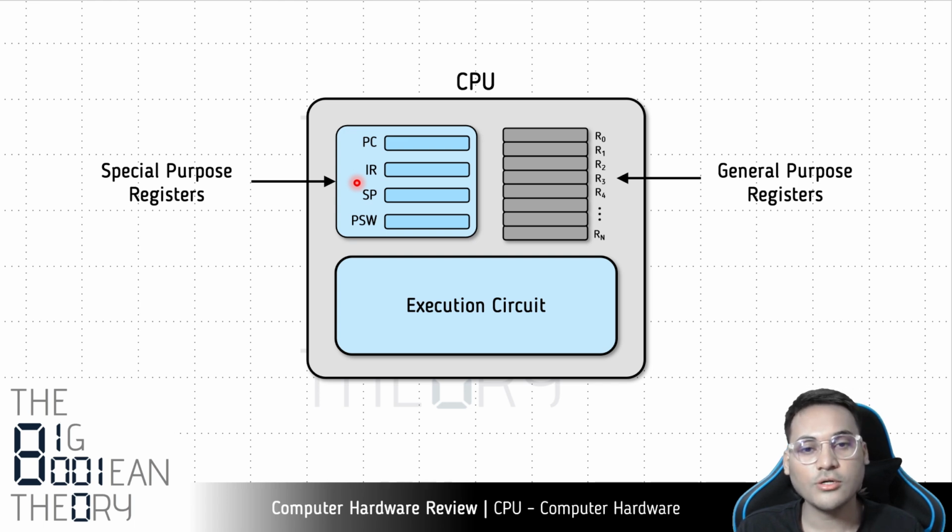And then let's talk about the program status word. Program status word is basically a collection of different flags, right? A register has many bits, and each bit is used as a flag in this program status word. As the name suggests, it denotes the status of the program execution. As your program is executing, the instructions are getting executed, and the status changes. Let us talk about some flags to give you a basic idea.